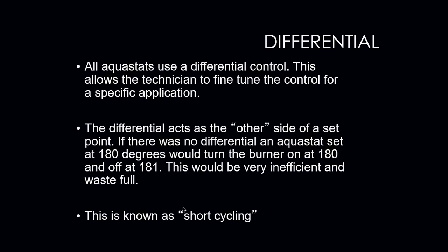Okay, all aquastats use a differential control, and this allows the technician to fine-tune the control for a specific application. The differential acts as the other side of the set point, and if there was no differential on an aquastat, say set at 180 degrees, that burner would turn on at 180 and then turn off at 181 degrees.